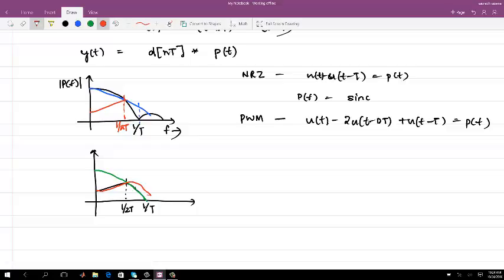But you can say that in PWM you have only one control, which is the duty cycle. In case of multi-tap pulse modulation, if you use multiple taps, then you have more control over it. So you can equalize very different channels, but PWM equalization is very constrained because you have only one degree of freedom. If you want more, then you try to use more different pulse widths, that is an extension of it.